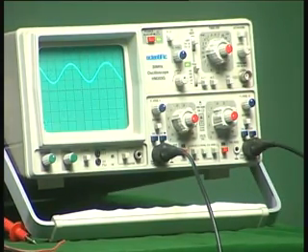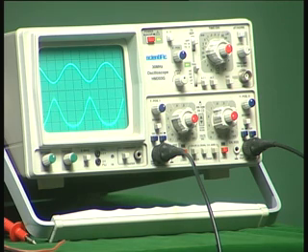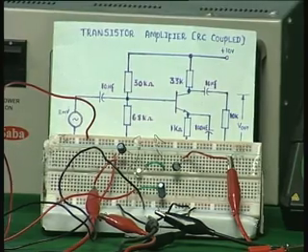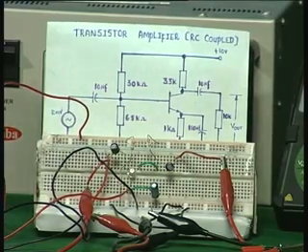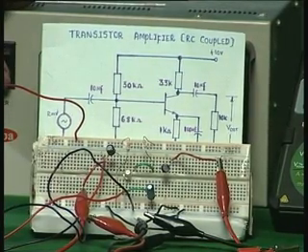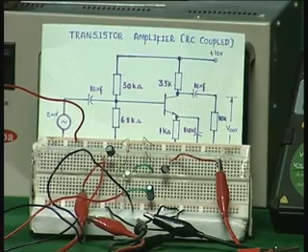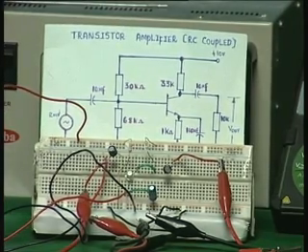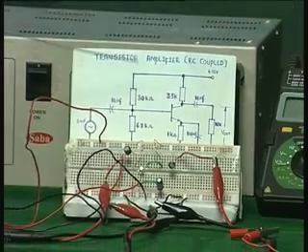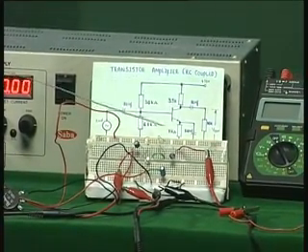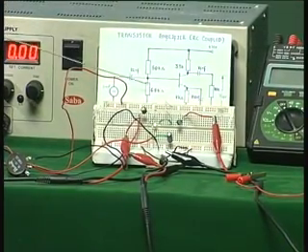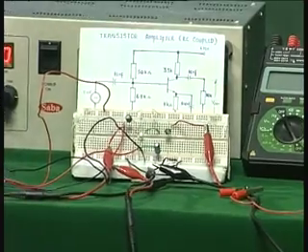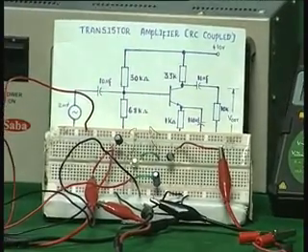So I just want to indicate to you that the choice of the various resistors, especially that RE, which is the biasing resistor, is very important in choosing the performance of the amplifier. So you do get amplification gain, even though we have not actually calculated what the gain should be in this case, but we do get enough amplification. So you can see the biasing circuit is very important. After that you have to use coupling capacitors, and this is the bypass capacitor. Once you do that, what you get is an RC coupled amplifier of a single stage.